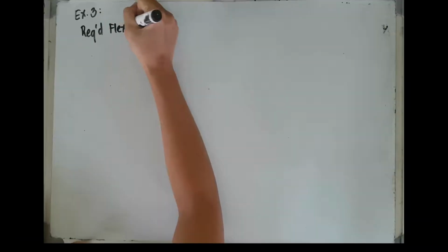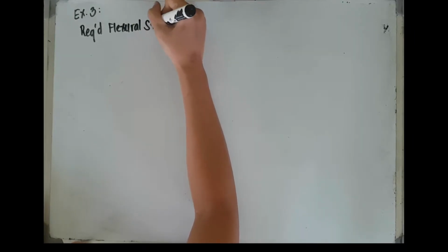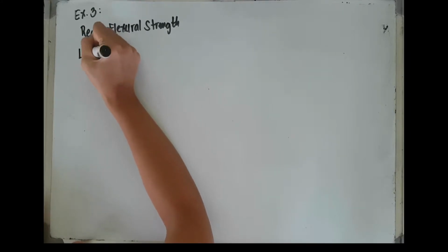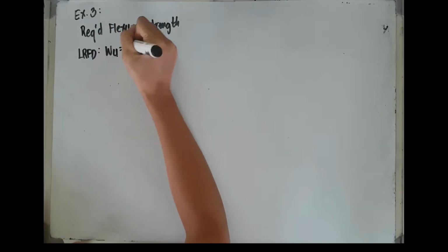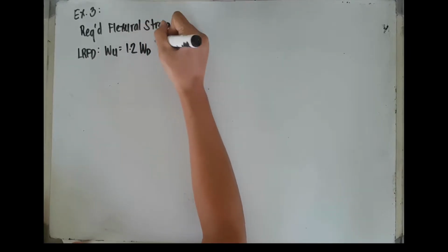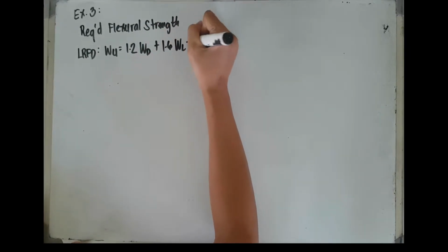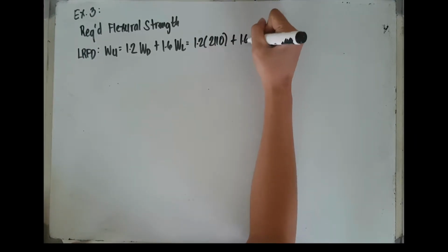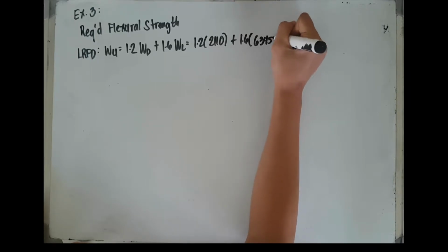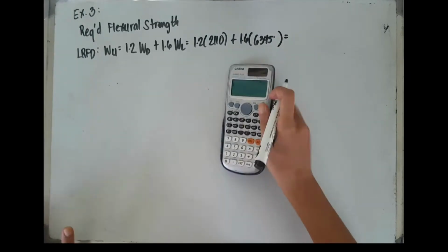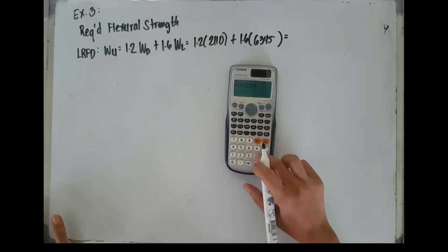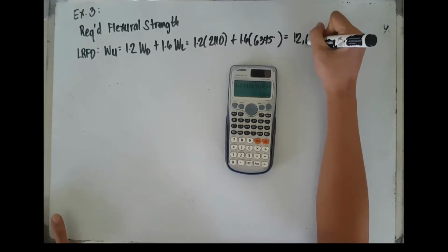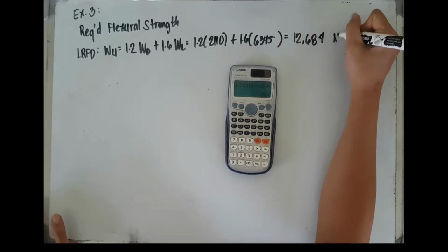Our first step is to determine the required flexural strength using LRFD and ASD. The load will be equal to 12,684 Newton per meter.